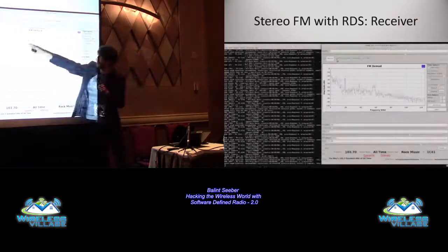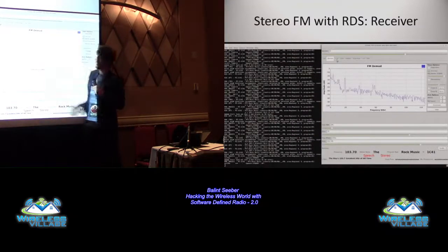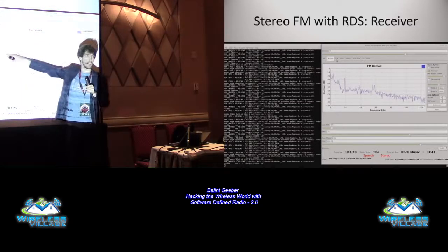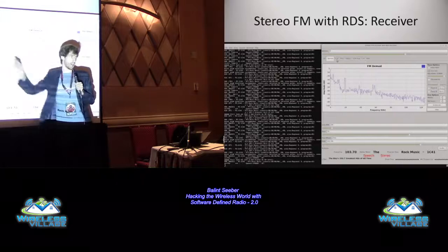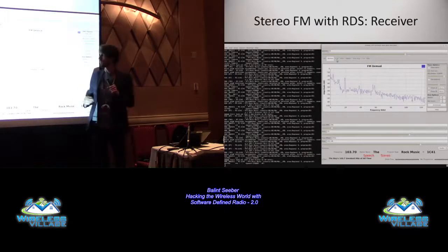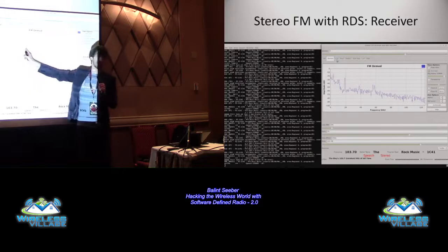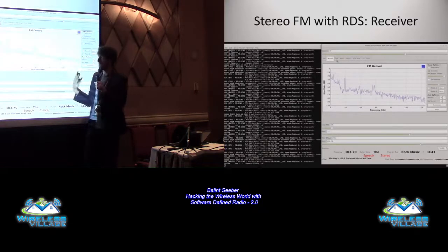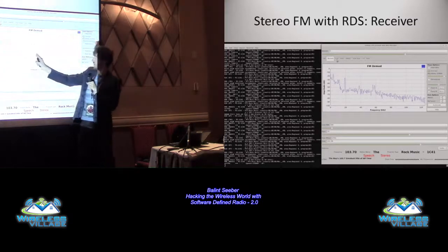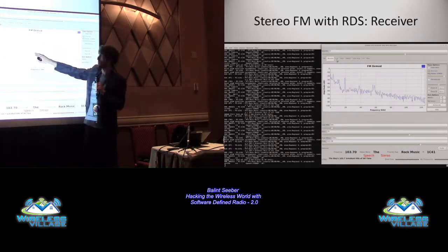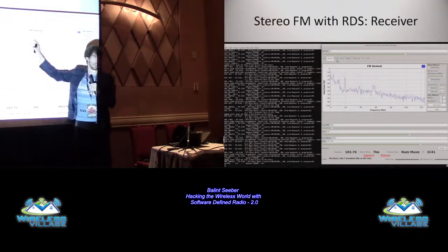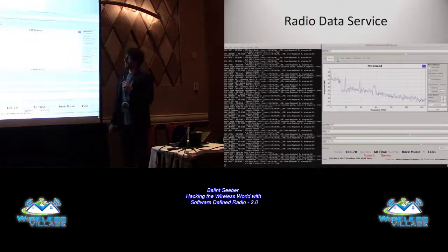And this is actually once you look at the demodulated portion of the signal. So this big peak here is the 19 kilohertz pilot tone. To the left-hand side of that is your mono, left plus right. To the right-hand side of this is your stereo difference channel, so that's left minus right, and then your receiver will combine the two to recreate your independent left and right channel, so you get stereo audio again. Beyond that, you have your RDS subcarrier up here. You basically multiply this pilot tone up to center in on that subcarrier.